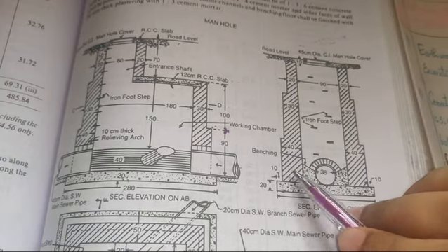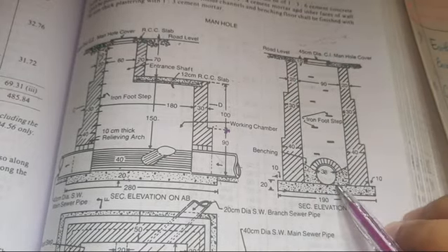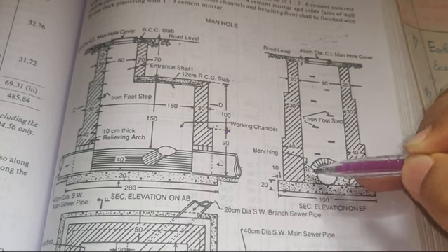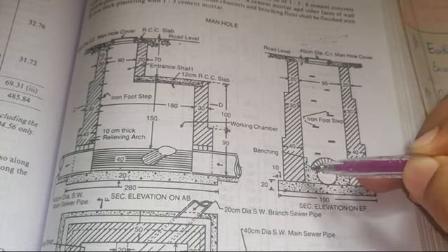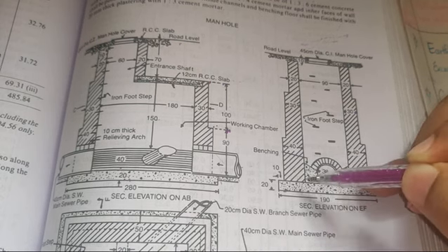So the width is 90 centimeter, that is 0.9 plus 0.38 divided by 2, which is the lump sum quantity they have calculated, because it would be very difficult to draw a straight line here and calculate the area of this triangle and the area of this rectangle. That would not be properly acquired because it is going circular like this, so you cannot get a proper rectangle here, right?